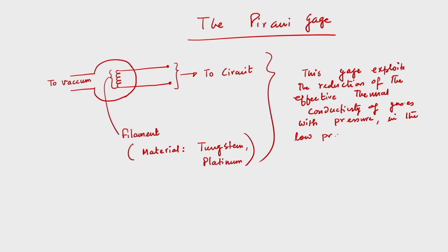I am saying in the low pressure regime because at a high pressure the change in thermal conductivity with a change in pressure may not be captured correctly, so we may not come up with a correct measurement of the pressure.